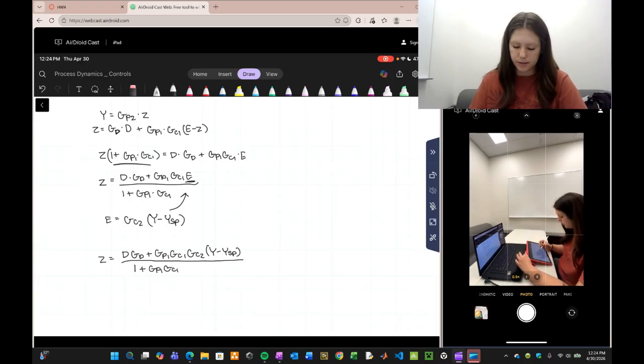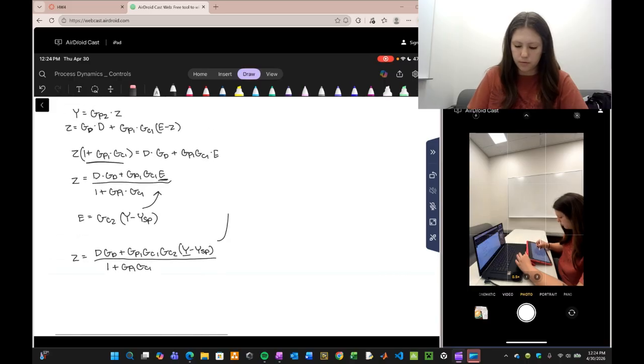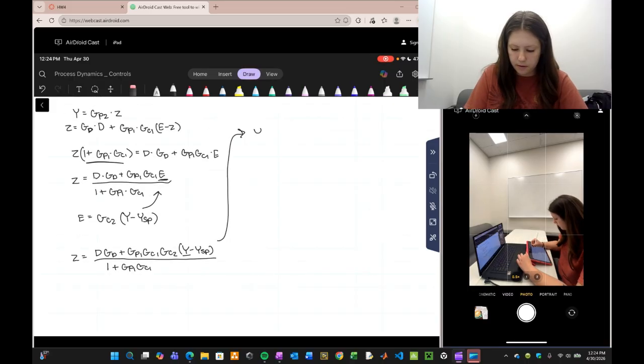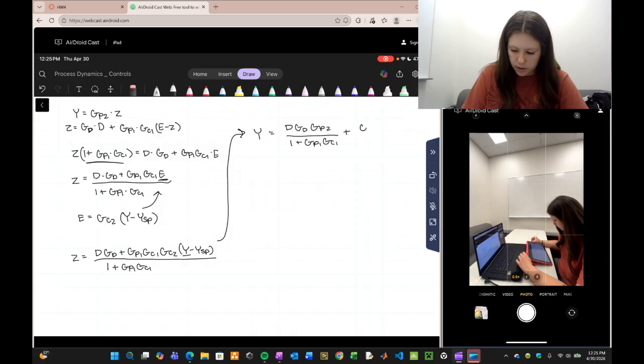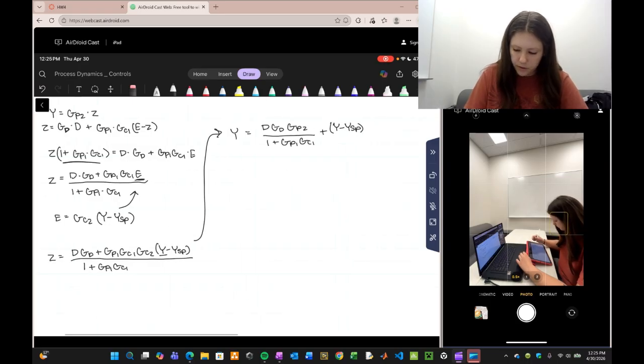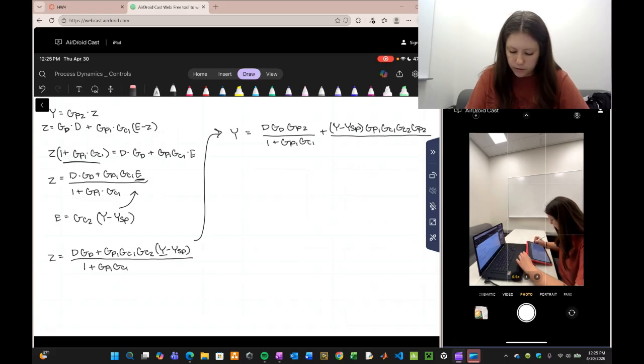So now we want to get Y alone, so I will come up over here, get Y equals D GD GP2 over 1 plus GP1 GC1, and then plus, or it'll be times Y minus YSP, GP1 GC1 GC2 GP2 over 1 plus GP1 GC1.